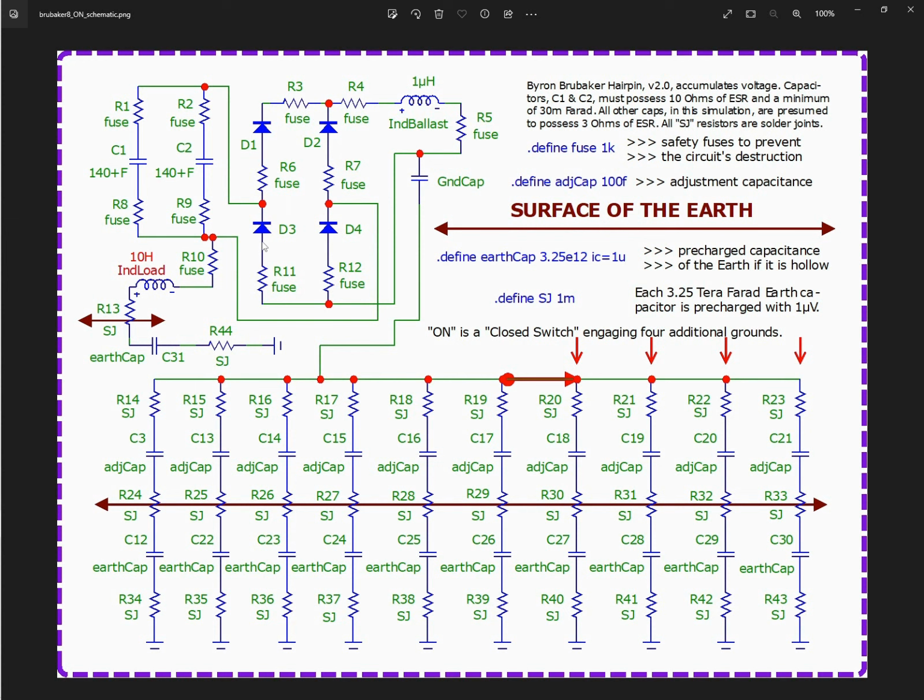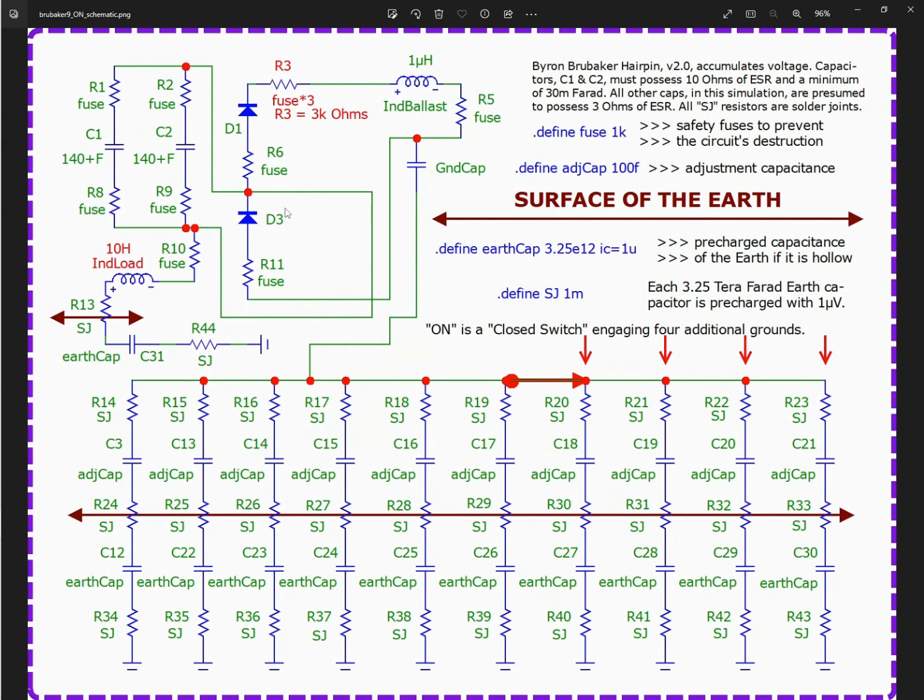But now how do I tell the simulator to do that? Oops. Well, I can't. I don't know how. I mean, if I built them, maybe I could, but I can't do it under simulations. So the best I could do was to simply take out both of these diodes on the right-hand side and bring this connection on the right that's just hanging there over to the left-hand side and short out the AC with itself, the AC loop. And that was the best I could do. But it turned out I didn't need those 2 diodes.